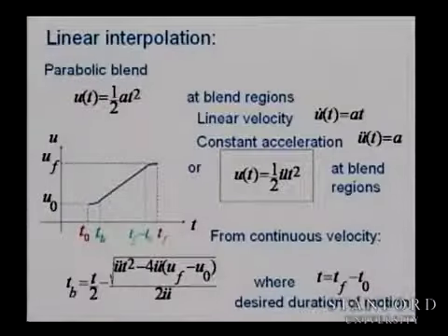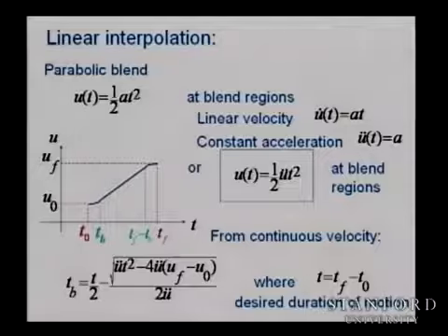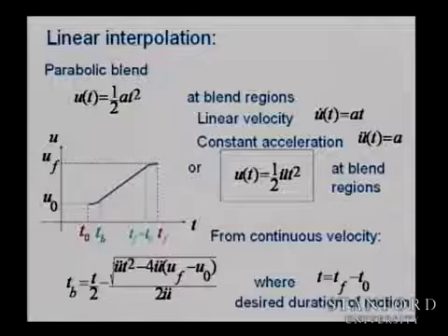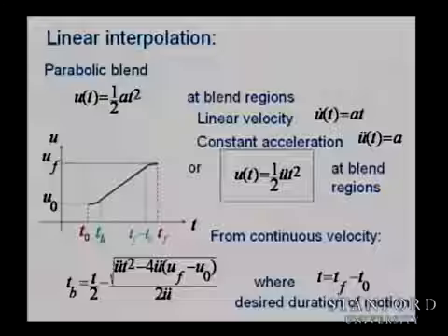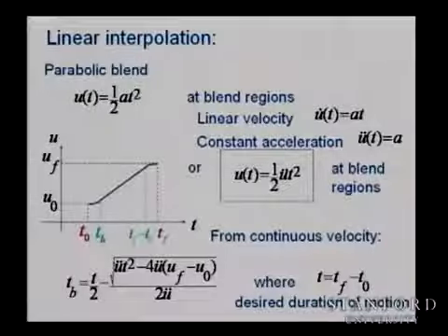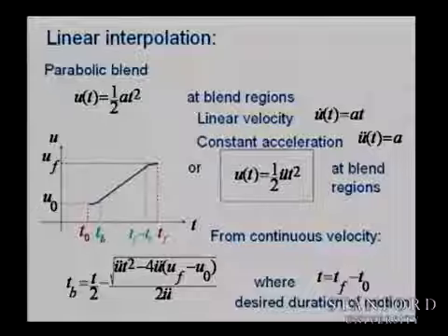They're a little bit more complicated, but it's basically a second degree polynomial, where t here is the duration of the entire motion from t sub 0 to t sub f. So we basically have here the equation for the motion using a straight line with parabolic blends in a continuous fashion from time t sub 0 to time t sub f.